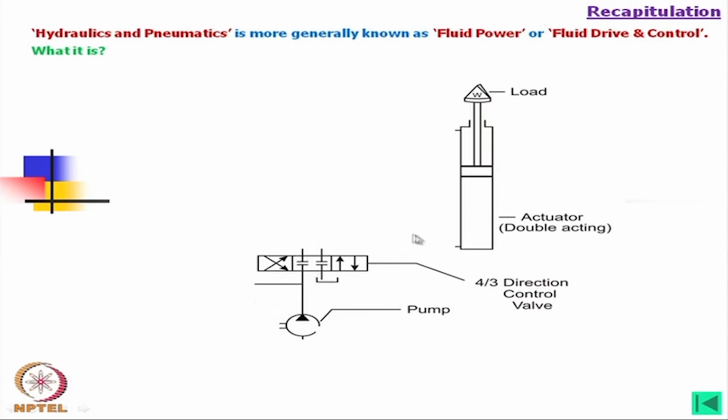So, this will pump the oil inside and it will go up, but the question is that next moment we have to bring down the piston for the next assignment. In that case, definitely this oil we have to allow to some other path, we cannot return this oil through this pump. So, now we will think of some arrangement by which we can do that.